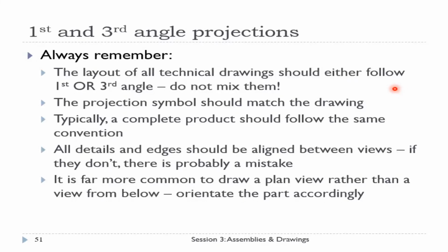There are a few rules that you must always remember. The layout of all technical drawings should follow either first or third angle. Do not mix them. If you are using third angle in a drawing, you can't combine it with first angle. The projection symbol should match the drawing. Again, if your drawing is in third angle, you can't create view layouts in first angle. And typically a complete product should follow the same convention.